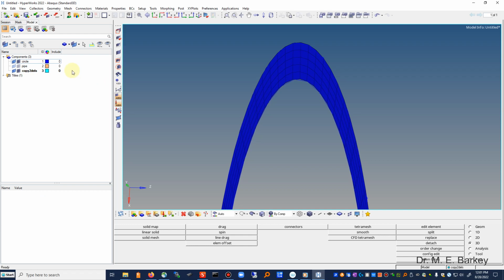Now here's some advice if you use this software with Abaqus. Try not to start your component with a name that starts with a number or anything weird. Use a letter, A through Z. Also, try not to put any spaces in your component name. You'll be better off when you use Abaqus later. If you do those things, you won't have any problem.